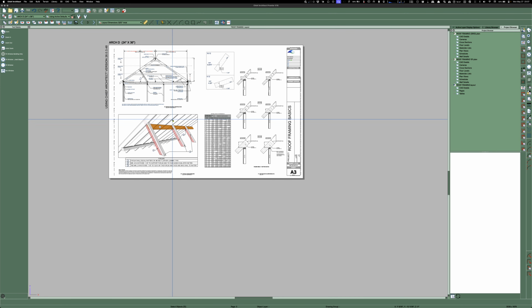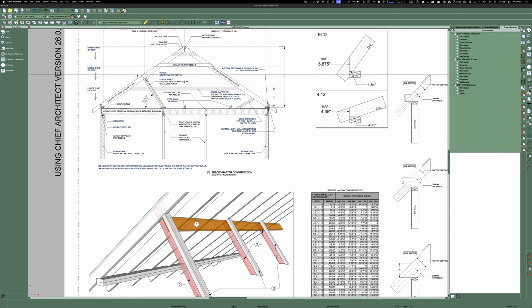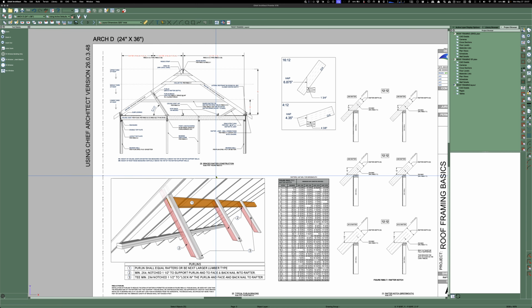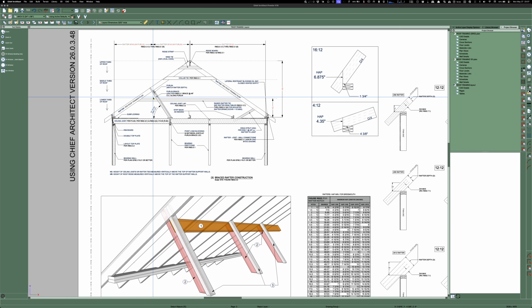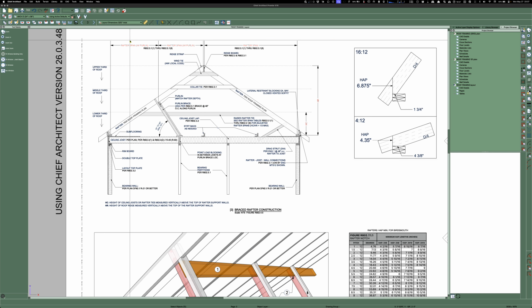Next page. So this is from the code book right here, R802.4.5. And I added things that I've either seen or I've incorporated into what I do. Like wind ties. That's a Germantown, Tennessee, what is that? The New Madrid fault line, seismic D2. You can do that, or you can use metal strapping.